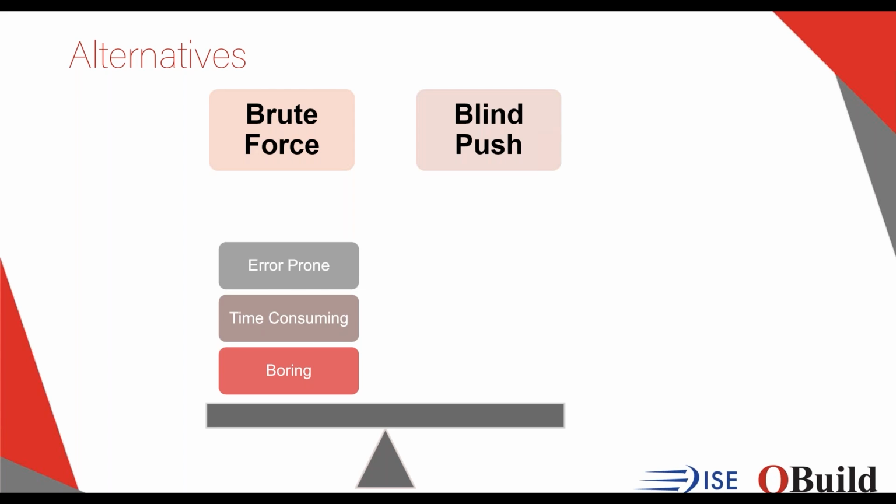So you can start to see some of the issues with some of these alternatives. Now, the second alternative that we see is blind push. When I say blind push, it's using a kind of import-export method. So maybe exporting your Inventor file or your CAD drawing to an Excel document, then massaging it, getting it prepared for XA to import, and then importing into XA following their format.